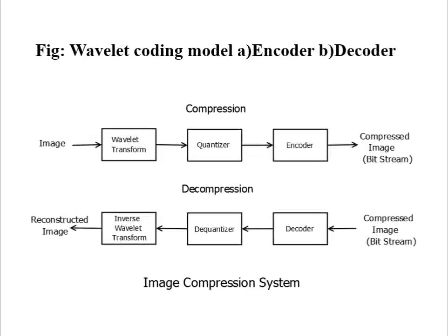When the transforming wavelet has a companion scaling function, the transformation can be implemented as a sequence of digital filtering operations, with the number of filter taps equal to the number of non-zero wavelet and scaling vector coefficients. The ability of the wavelet to pack the information into a small number of transform coefficients determines its compression and reconstruction performance. The most widely used expansion functions for wavelet-based compression are Daubechies wavelets and biorthogonal wavelets.